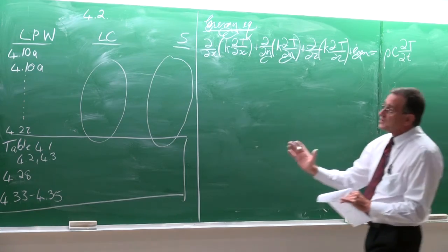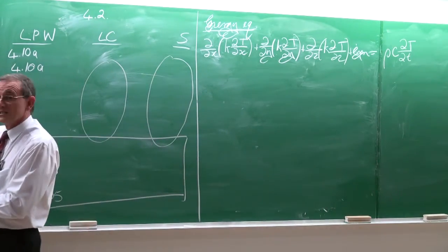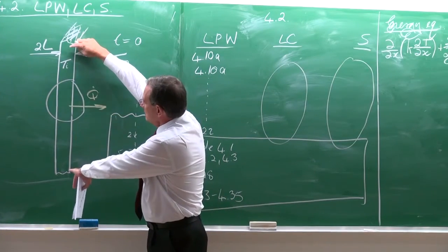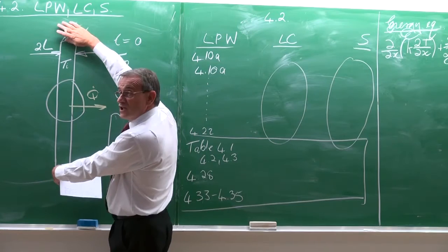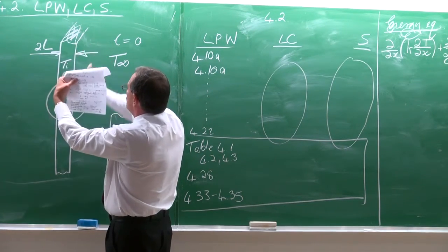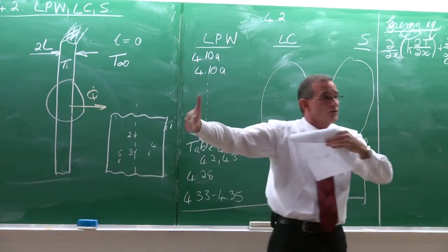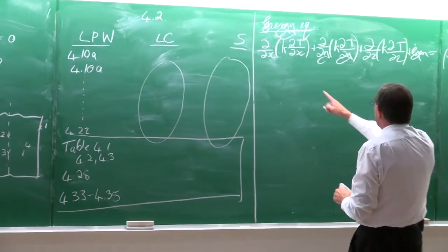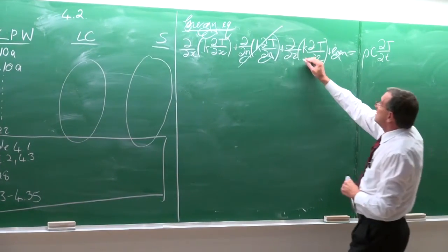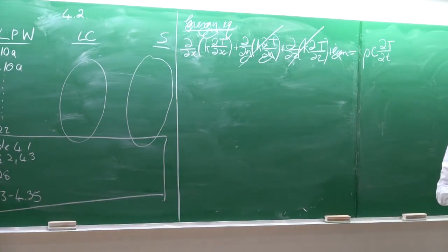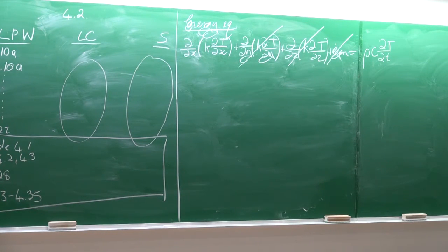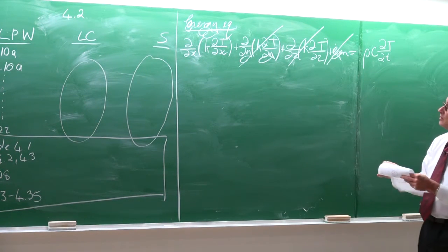If we now look at this problem, remember we've made the assumption that the heat transfer is only in one direction. In this direction it's very long, so the heat transfer is negligible or insulated, as well as on the other two sides. There's no heat transfer in that direction. So the heat transfer rate in the y direction is 0, and the heat transfer rate in the z direction is 0. And fortunately, there's no E gen on the inside. So the resulting equation looks like that.